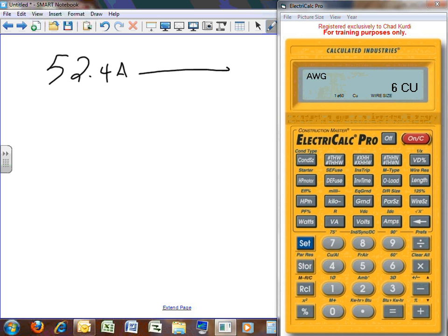Now you're going to take it to 310.15 B16 under the 90 degree column. Anybody tell me why I am going to this table under the 90 degree column? Because we're derating. The only time you touch that table is under derating. Can you guys find me a conductor that can carry 52.4 amps under this column? Copper, of course we're doing copper, right? So I have 52, it's going to be number 8.